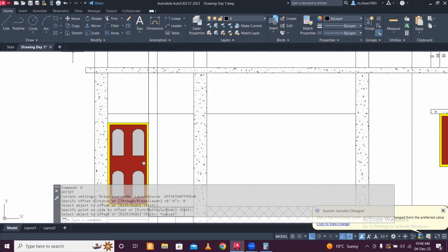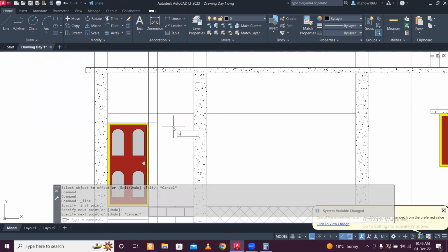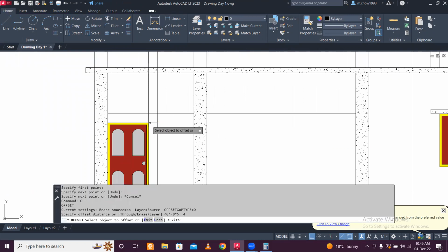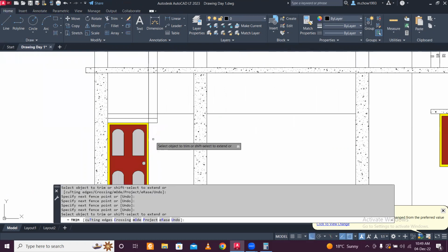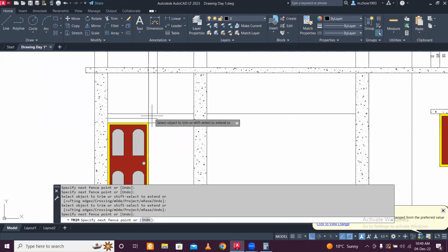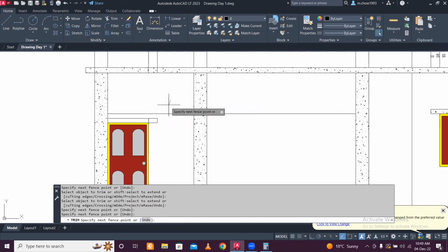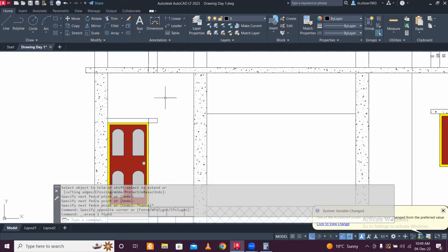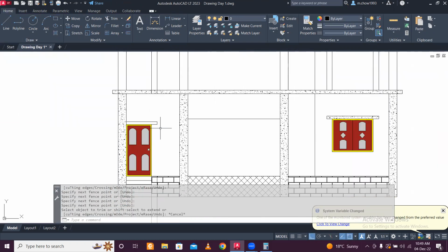And let's go and create a line here. Okay, line here, and 4 inches for the RCC of the chajja, like we've taken into case of, and trim the portions which you really don't need, right? And we escape, and we don't need this really as well. Trim this, and then hatch it.